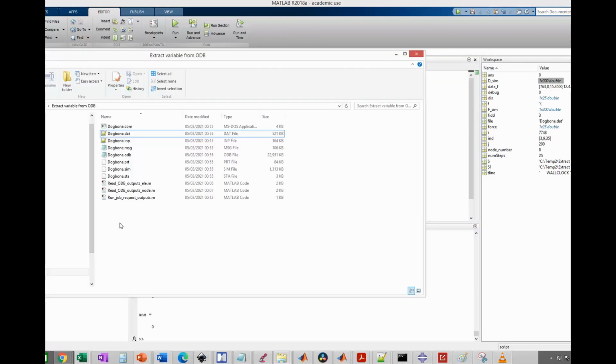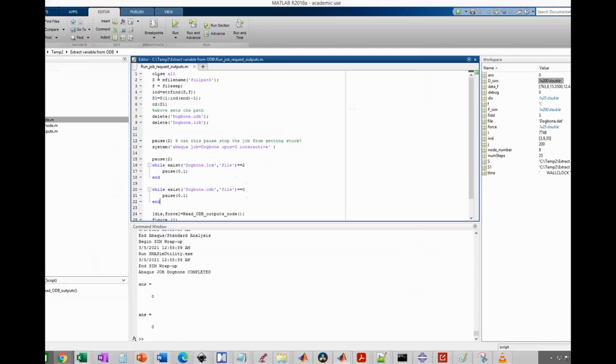This gives great flexibility because as long as you have these three Matlab codes and your input file in the same folder, you don't have to add any additional directory or set any path, not for Matlab and not for Abaqus. Lines 2 to 6 take care of that.